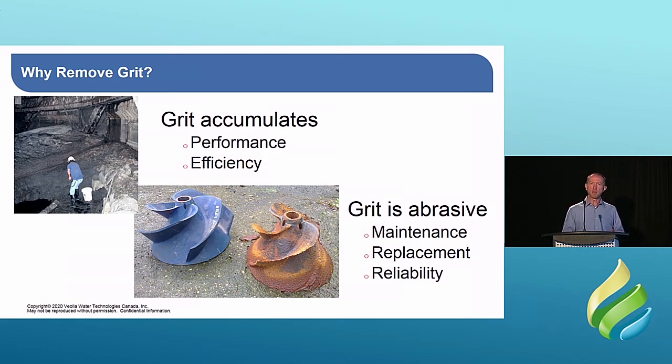I think it's safe to say that for most mechanical plants, probably just about all mechanical plants, grit removal is a useful thing. Even on lagoon systems, grit removal isn't a bad idea because it just fills up your lagoon with inert material if you don't remove it. So it's a pretty common thing on most wastewater plants these days.